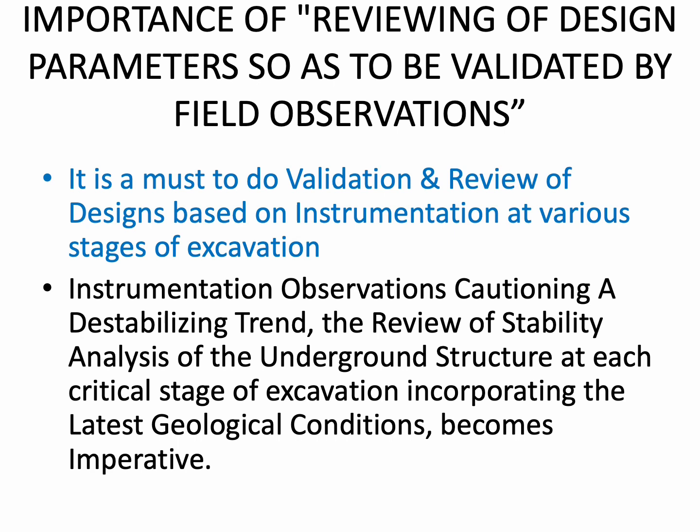Reviewing of design parameters so as to be validated by field observation. It is a must to do validation and review of design based on instrumentation at various stages of excavation. Instrumentation observations cautioning a destabilizing trend, the review of stability analysis of the underground structure at each critical stage of excavation, incorporating the latest geological condition becomes imperative.